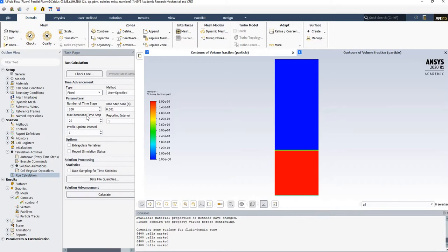So what is Courant number? You can check in the web or in the ANSYS help option as well. The way it is, that is actually directly related to the element size, the velocity you're introducing, inlet velocity, and not only the inlet velocity, the velocity all over the domain.